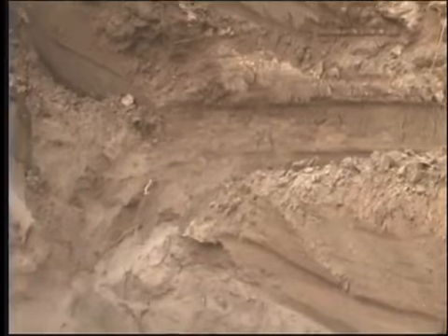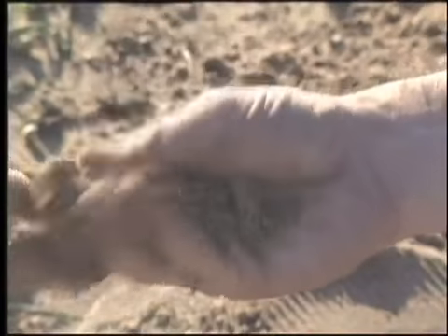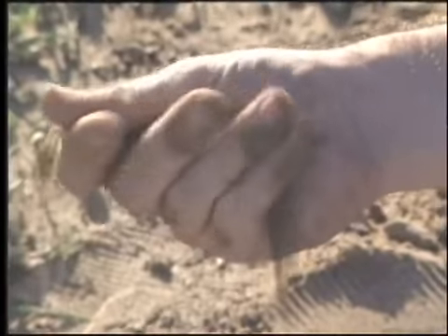Before digging the entire trench, dig down to the required depth and examine the soil. Take a handful of soil from what will be the trench bottom. If it forms a 1/8 inch diameter ribbon when rolled between the palms of your hands, the soil is too wet to work with. If the soil crumbles, digging may proceed. If the soil is sandy and will not form a ribbon, as described above, don't worry about the soil moisture.